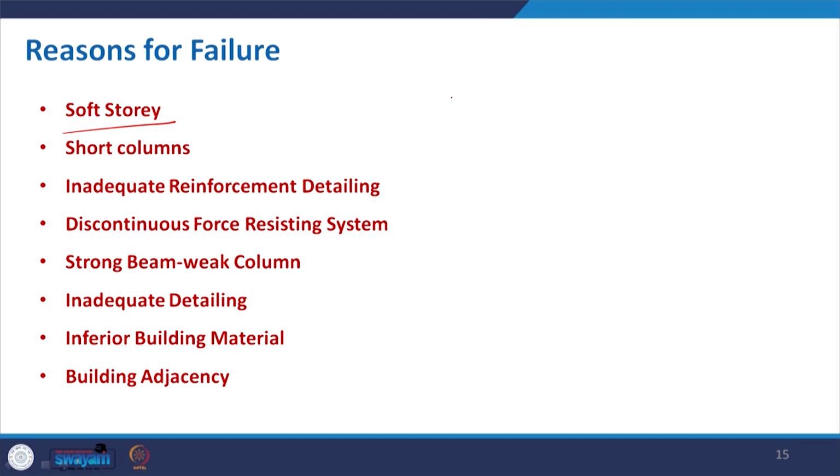And this is one, and the other things that we should do to make our building safe for this kind of disaster through different measures, like selecting the right material and selecting the right building form, that we will be discussing. So, in the reasons of failure, if we focus on this slide, it is related to the soft story. A soft story is basically where a building has heavy mass, but the ground floor is supported with only some columns. Normally this is very common for apartment buildings, where the ground floor is used for parking or any shop area.